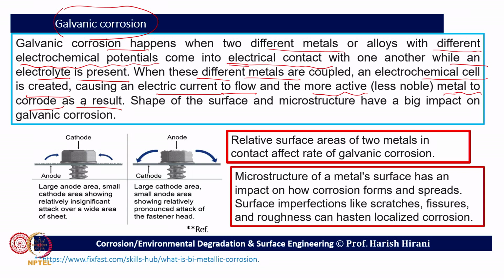So, only one metal corrodes. Now, suppose there are a number of materials available, some cheaper, some costlier, or when we make a complete structure, one interior part is more difficult to remove while the top surface is easy to remove. I can arrange the galvanic corrosion to save the inside material. I can make the outer surface less noble, so the complete corrosion will occur on the outer surface, which is easy to replace and visible to us. That kind of science can be utilized, and we can design in this manner.